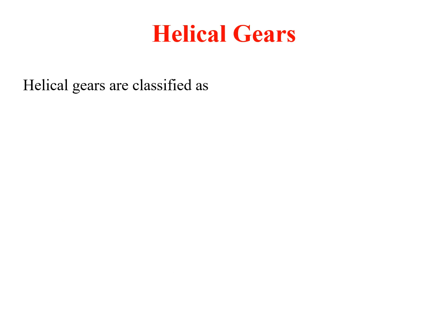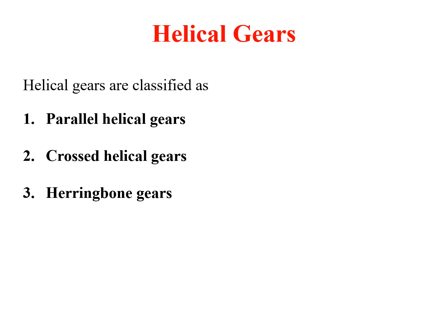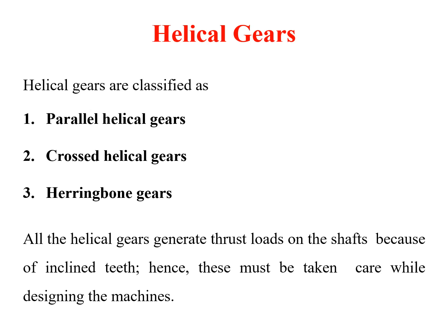Now further, helical gears are classified as parallel helical gears, crossed helical gears, and herringbone gears. In the case of all helical gears, thrust load is obtained. So basically, we have to consider this thrust load while designing any component, machine or gear pair.